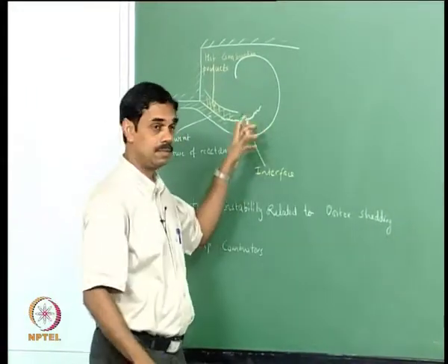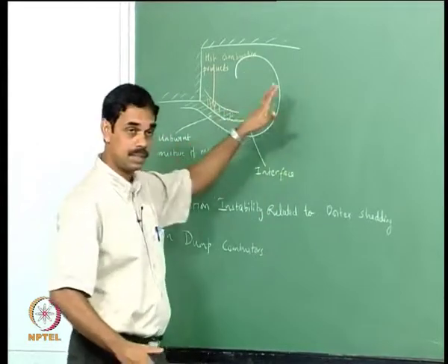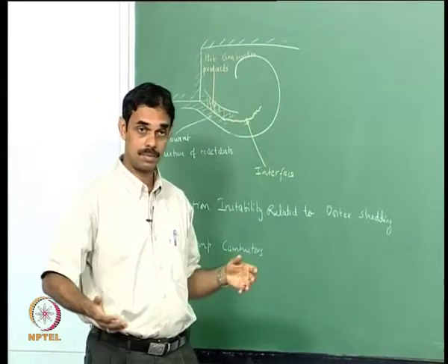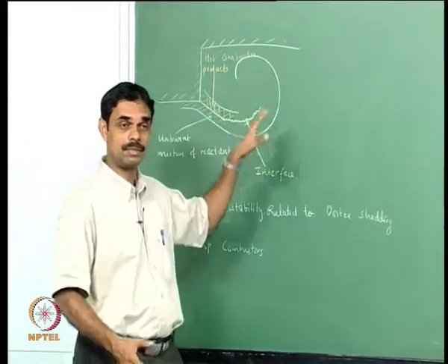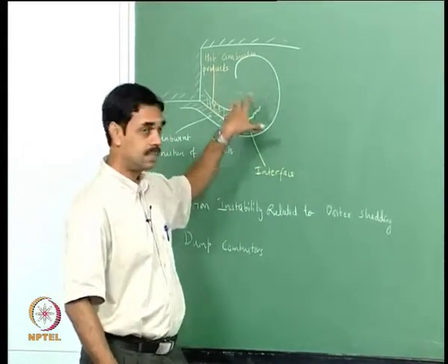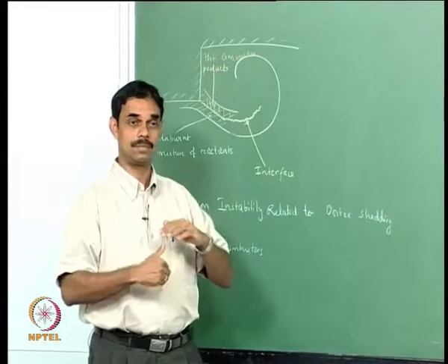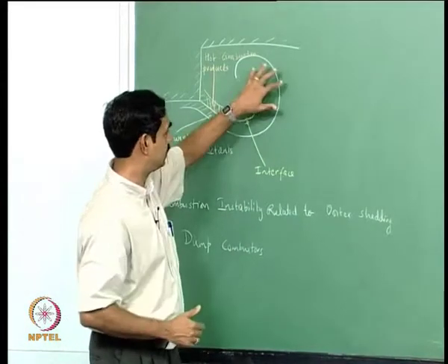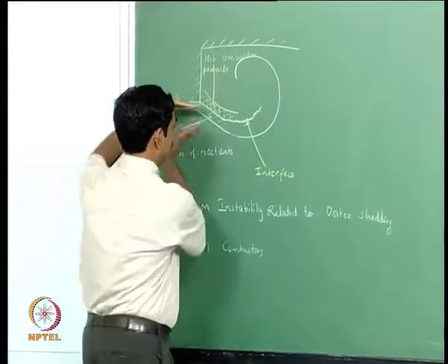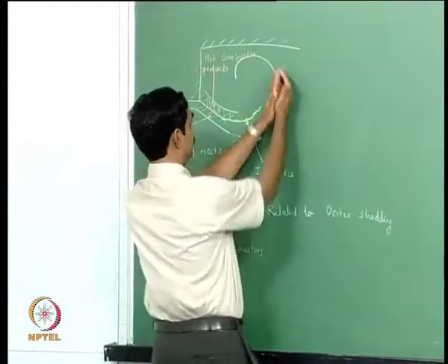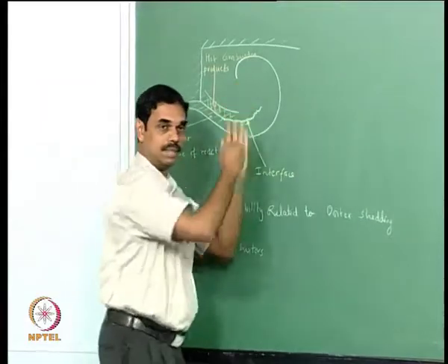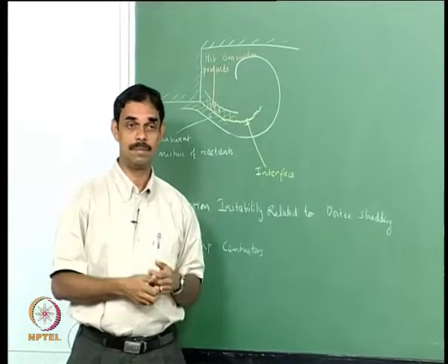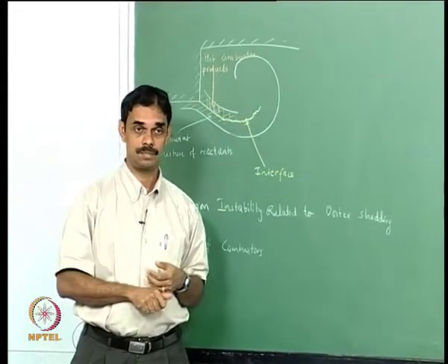If you do not have the big scale and if you have small scale turbulence right from the beginning, then you will have continuous combustion, but it does not come right from the beginning. The fine scale turbulence is happening as the vortices roll up. So initially this is not a steady picture, it just comes like this, then rolls up. Until it starts rolling up, the fine scale turbulence will be minimal. That is what I understand.